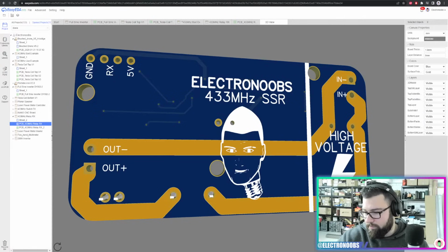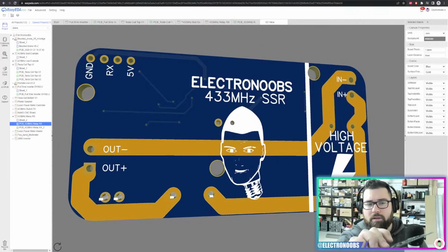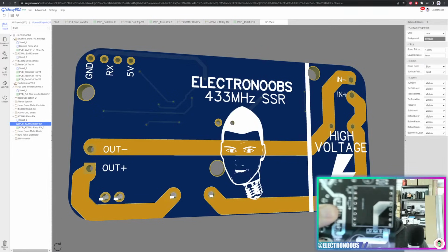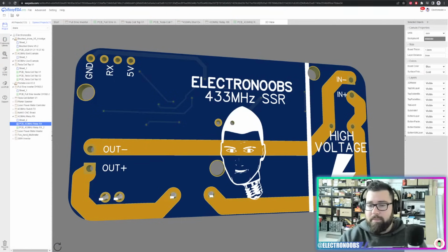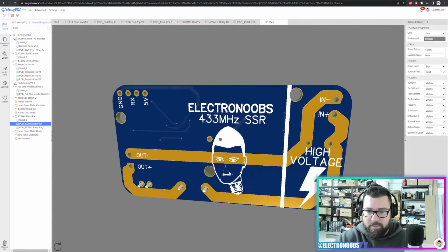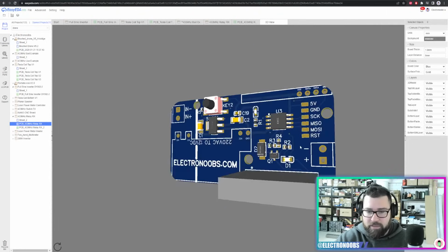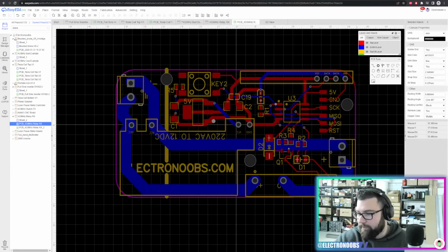Let me just place the OBS so I can see the picture. These MOSFETs here. Oh, this won't focus. Anyway, the silk screen on the MOSFETs won't appear on the tracks, because anytime that you have exposed copper like this one, the silk won't appear. On this 3D animation it will appear, but on the real PCB it won't. Don't worry about that. Let's just see other questions.